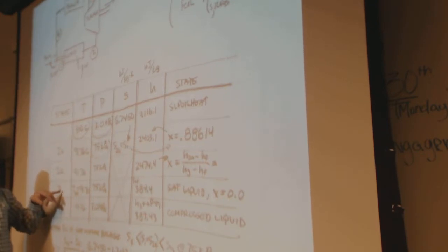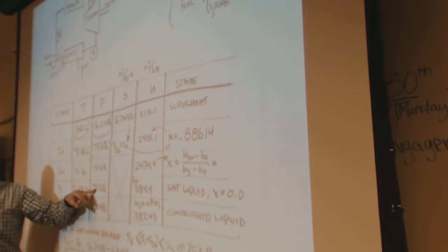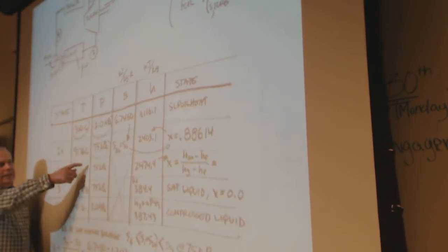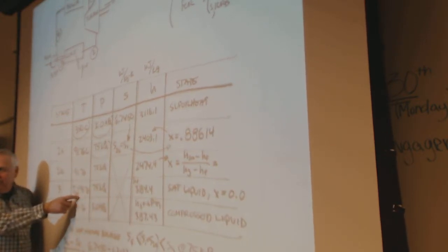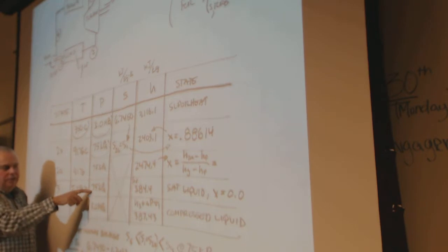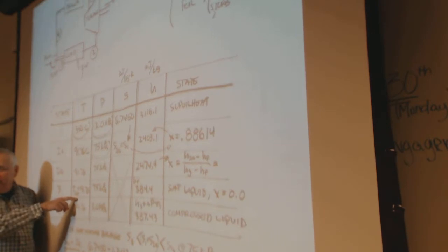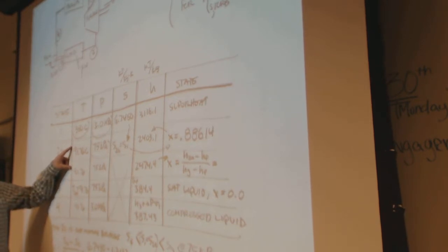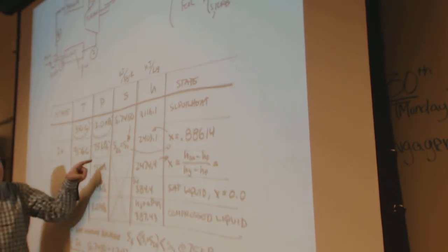What we know for sure is step 3 is at 75 kilopascals. All these pressures are what's real, and the temperature kind of jumps around in the phase and all that. But these are all going to be at this pressure. What we know is that here we're going to be at the saturation temperature, because it's just condensed water at that pressure. This is a little bit below atmospheric pressure, and a little bit below the boiling temperature of 100 degrees C. We don't know for sure about this point, except in the perfect world, we know that